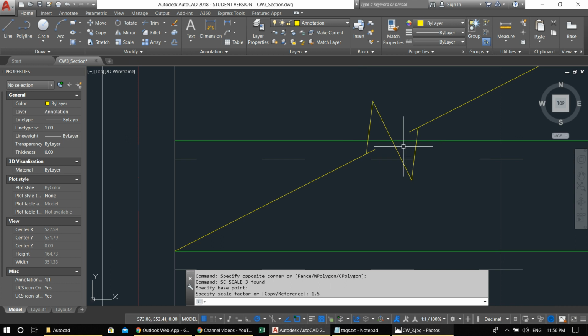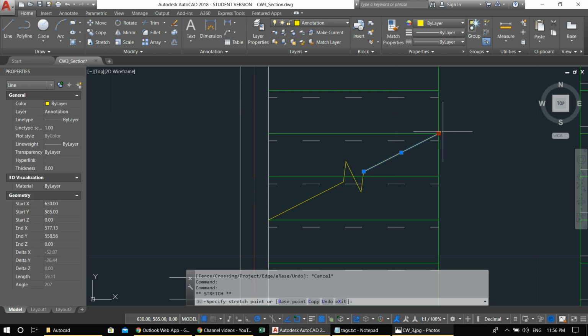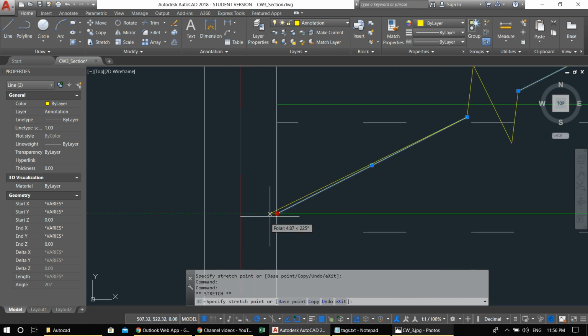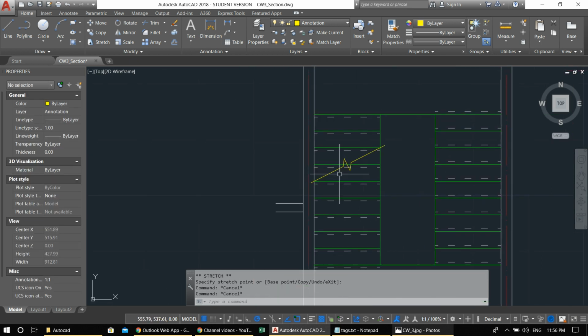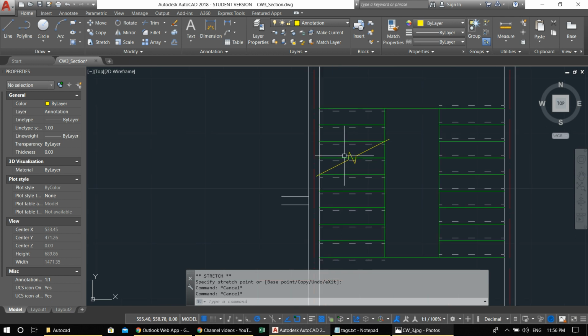1.5 times bigger. If you want to make it look a little bit more architectural, you can always pass this a little bit from the two sides. AutoCAD will show you the continuity of the line. Okay, now from this point on, it will be all dashed lines.